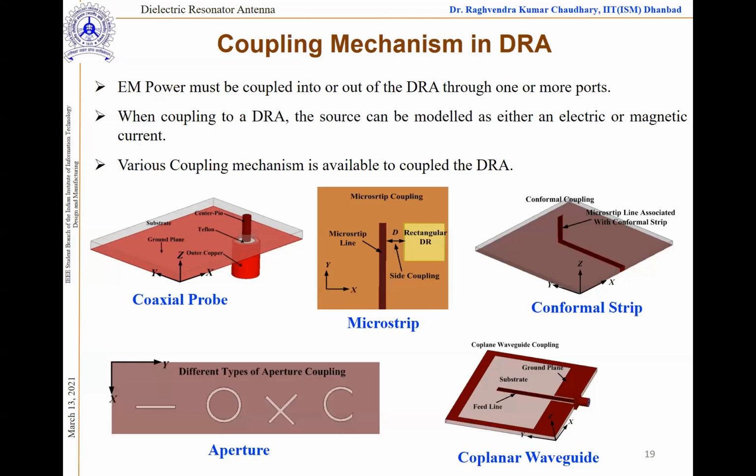If you open it up, there will be a very small pin just before the waveguide starts, and the current is there, and due to the current you have the magnetic field, and the position is at the middle so that you get the maximum.